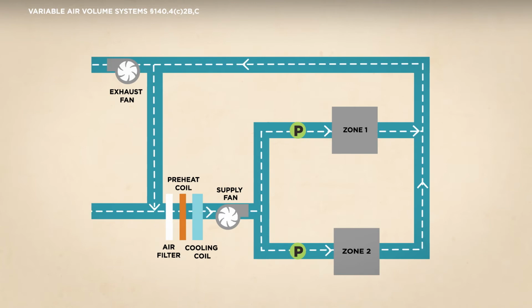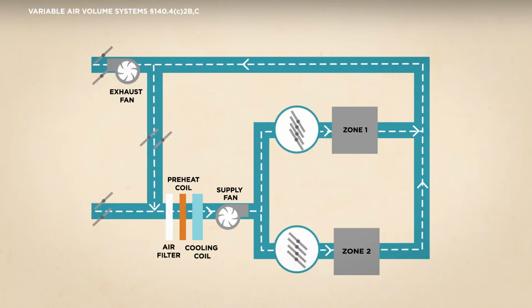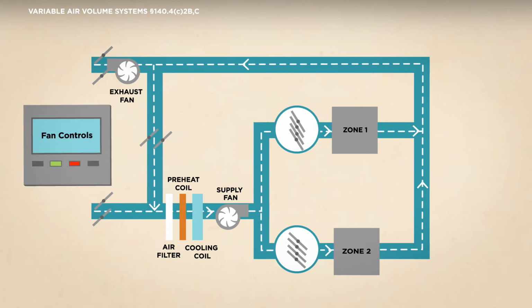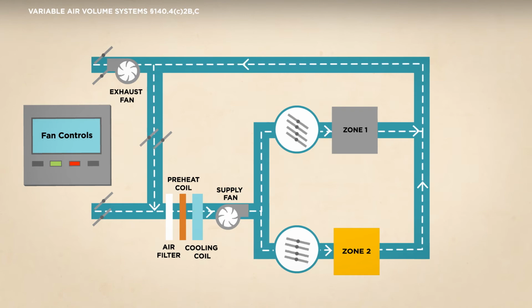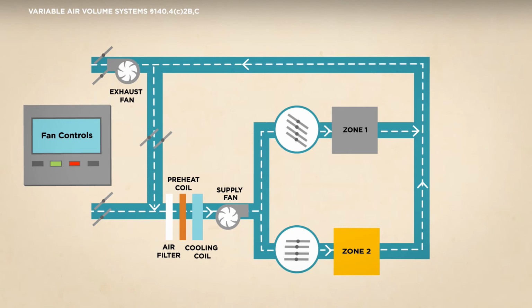This requirement does not apply to multi-zone systems with direct digital control of individual zone boxes that report to a central control panel. For these systems, static pressure set points must be reset based on the zone requiring the most pressure. The purpose of this is to dynamically reduce the duct static pressure set point as low as possible while maintaining adequate pressure at the zone box with the greatest demand. Dynamically resetting duct static pressure saves energy by reducing fan power consumption.